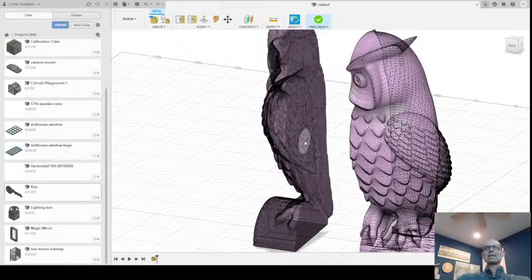So that's the way to split mesh bodies. You pull them in as STLs, the only way to get them being something like Thingiverse. If you want to make some kind of tweak or modification, or resize, or split the object up so you can fit it on your bed, whatever your challenge is, you right click, insert the mesh, much like we inserted the DXF. Once the mesh is on the workspace, you can right click on the mesh itself, click edit, and that will pull up the mesh tool set that you see represented on my screen.